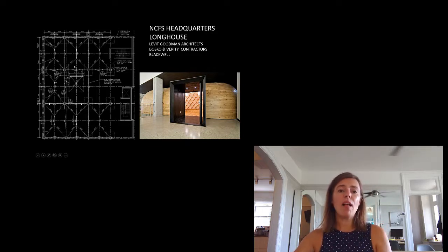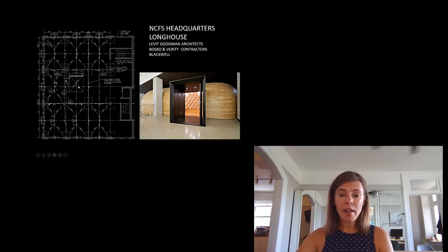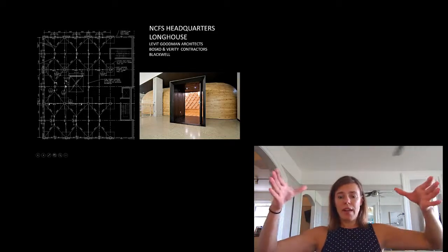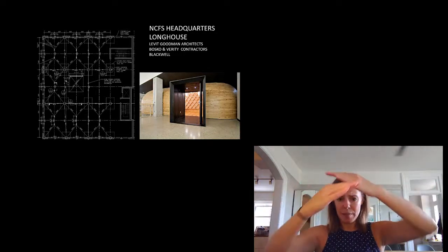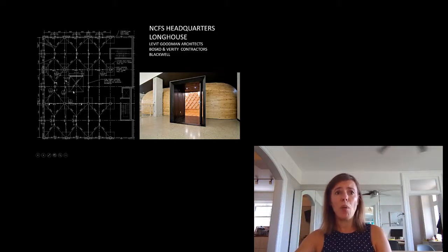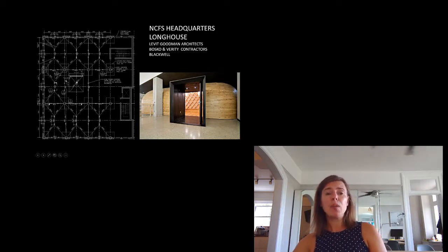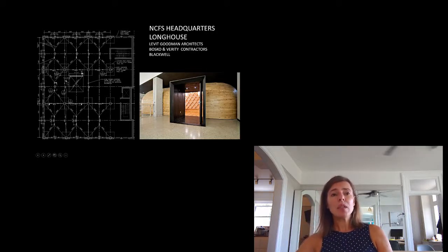The main building itself was a concrete building, 4-story concrete building, existing building that they wanted to cut this opening in here in all the floors. So obviously we're cutting the concrete and all the reinforcing steel that's in it. You can imagine these little things here are the columns. This is right in the middle of it. If you've ever kind of held up a bed sheet at the 4 corners before it's on the bed, you know that where it wants to sag is in the middle. So these middle points, right where we cut the hole, is where we were kind of cutting it out. So it wasn't too bad. That took some work and calculations, but it wasn't horrible.